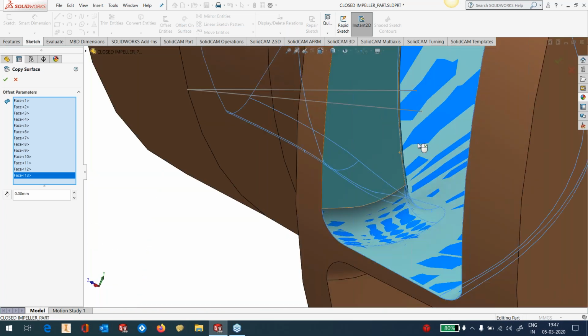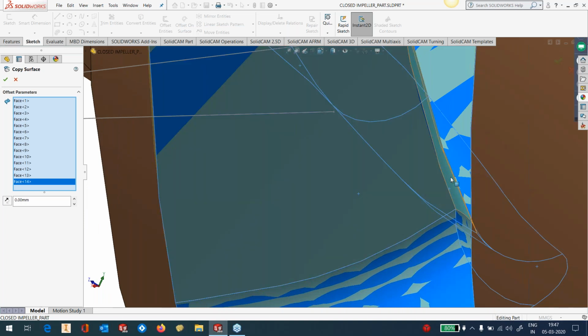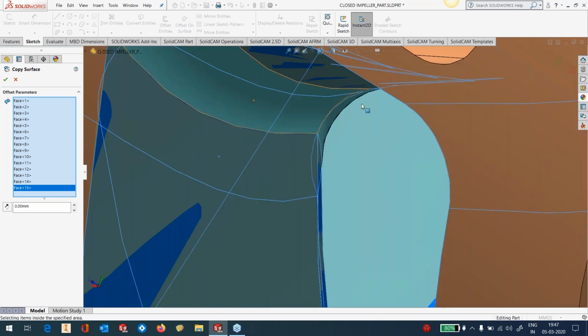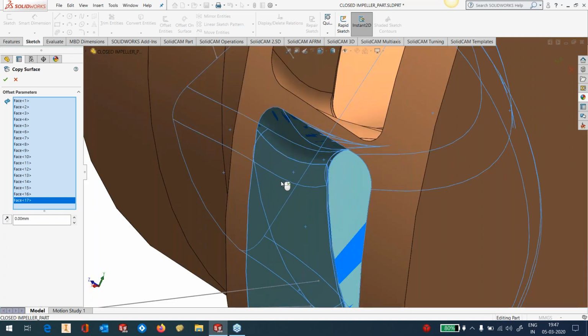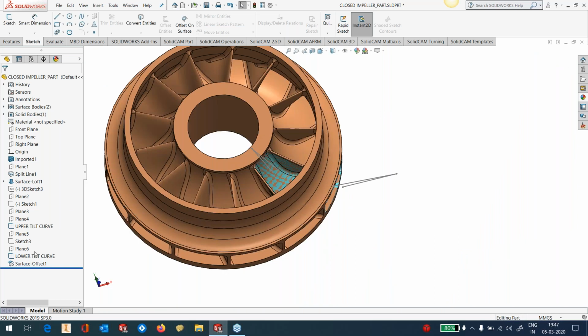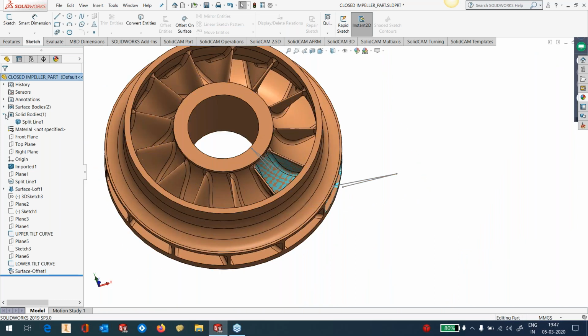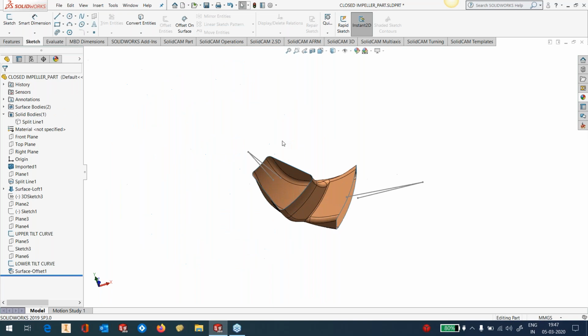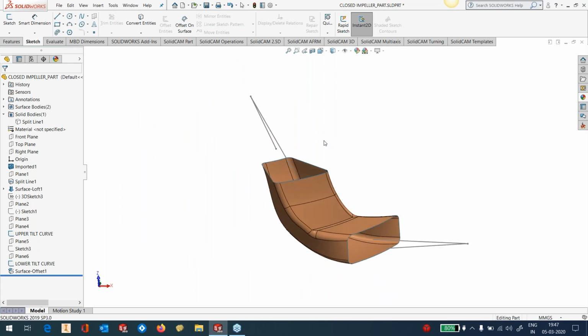Okay, this one here, this one here, this one, and this one. Okay, this is done. Let's go up here, and I'm now going to switch off my solid part and see. Now you see why it's necessary to isolate the surfaces, because it's now easier to visualize. Now, because we are going to machine one from the top, one from the side, I prefer to have separate geometries for these. So how do we create it?